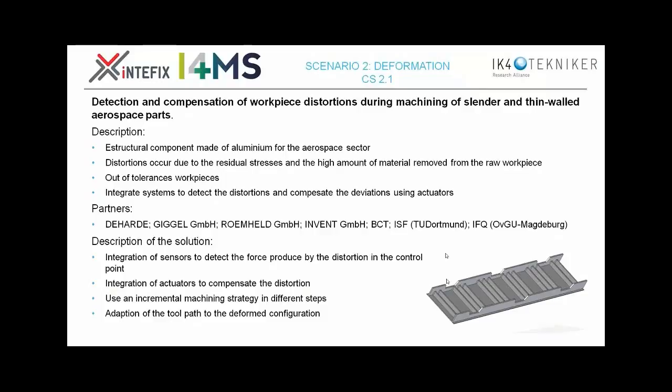Then with that information, they will try to compensate the distortion through movement of the positioning pins, and also by changing the clamping force.